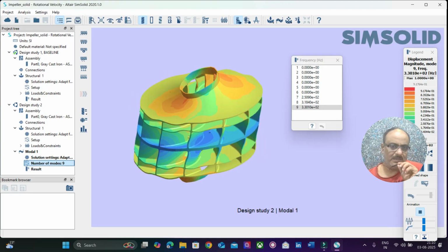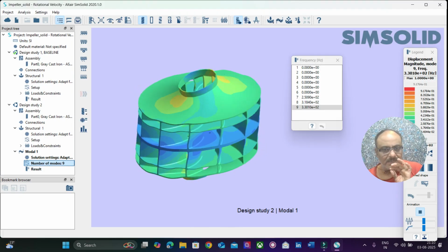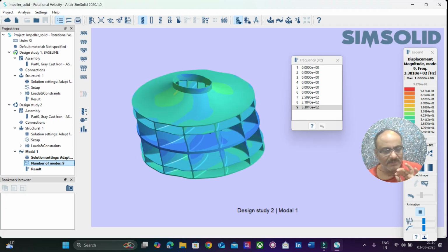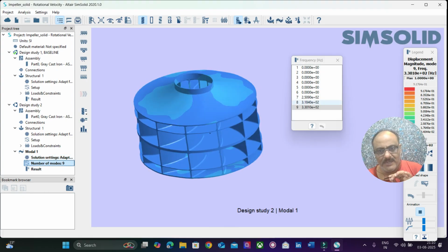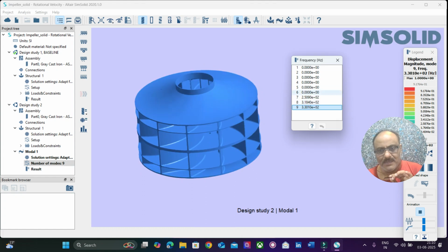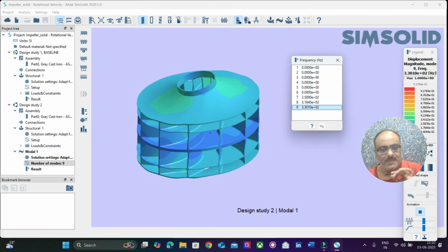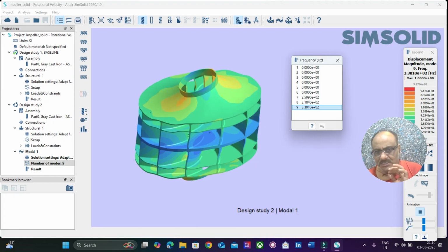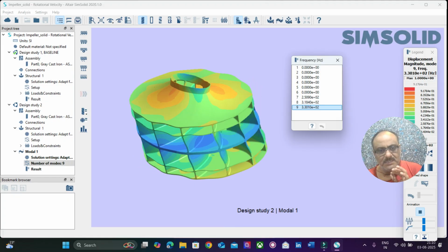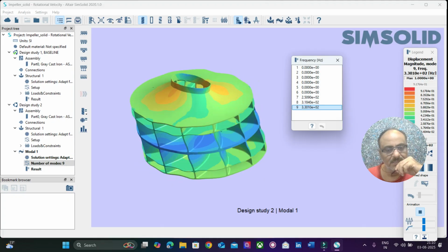Now let's conclude here and revise what exactly we did. This is a normal mode or modal frequency simulation, where the fundamental frequencies are extracted, and we have 7, 8 and 9 here in the tabular column as the frequencies. This is the first natural frequency N1, this is N2, and this is N3. From the previous episode, from the structural deformations, we found that the structure was safe from the stress as well as the deformation perspective. The next episode will focus on forced frequency or forced responses.